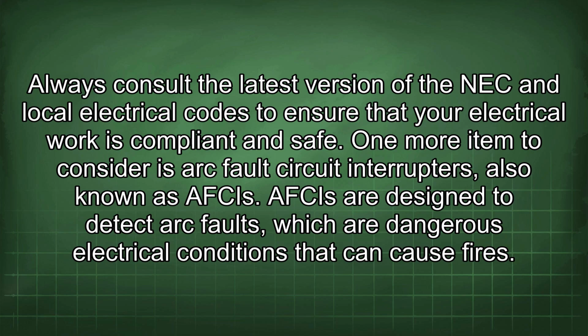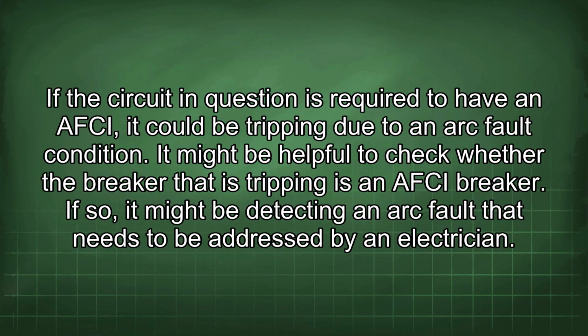One more item to consider is arc fault circuit interrupters, also known as AFCIs. AFCIs are designed to detect arc faults, which are dangerous electrical conditions that can cause fires. If the circuit in question is required to have an AFCI, it could be tripping due to an arc fault condition. It might be helpful to check whether the breaker that is tripping is an AFCI breaker. If so, it might be detecting an arc fault that needs to be addressed by an electrician.